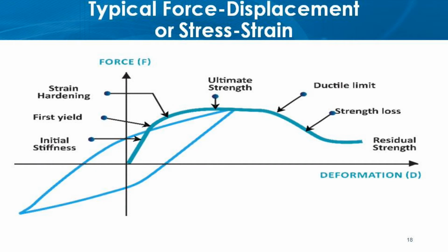Second part of the story is this: stress and strain do not have a relationship which is constant all the time. In fact, it is changing all the time. If you start from this point at 0 stress and 0 strain, and you start with a little bit of strain, with corresponding stress, after some time, the relationship between them will no longer be linear. The structure will start to deform faster. And then if you go to this point, it will also become flat.